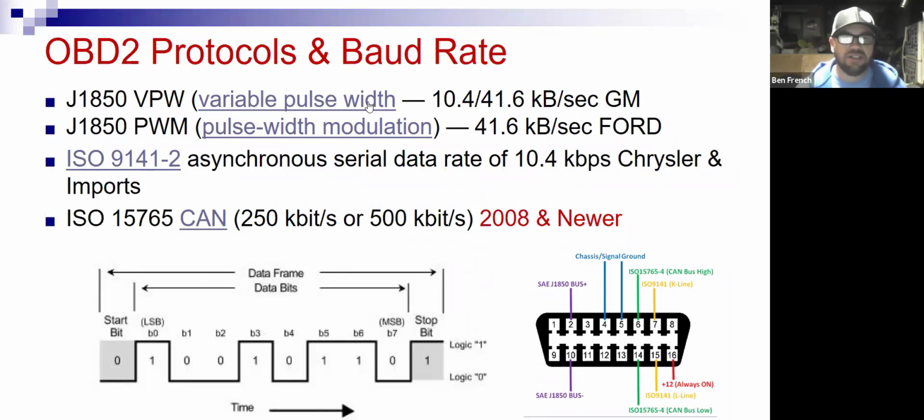And what you want to look for is after you're done with your repairs, drive it around similar to how it was being driven in the freeze frame. So if the car was, let's say, under 30% load at 60 miles an hour with a hot engine in your freeze frame when the code was set, I would drive the car the exact same way to try to recreate that condition. So hopefully that answered that question in the chat.